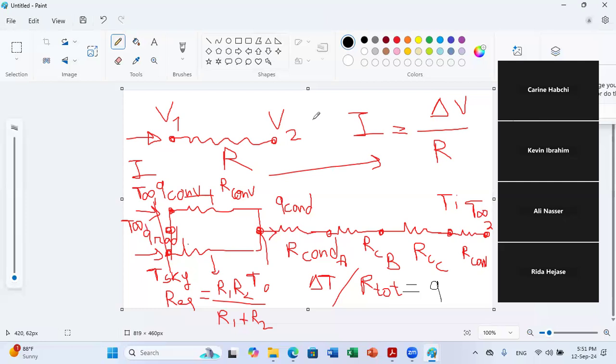That's why we study the relative direction of the sun, to know which facades are exposed to sun during winter. We put large glazing ratios on these facades, while for facades subjected to the sun during summer, we try to minimize windows and the total glazing area. So this shows the importance of relating our basic knowledge of heat transfer to applications in the energy field.